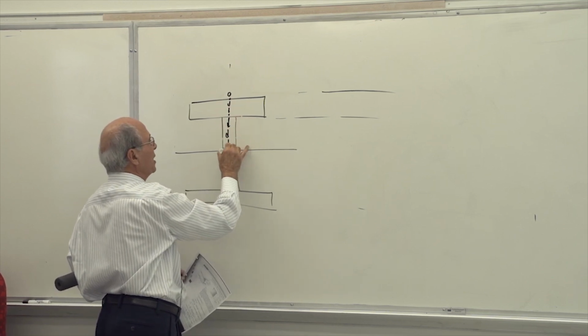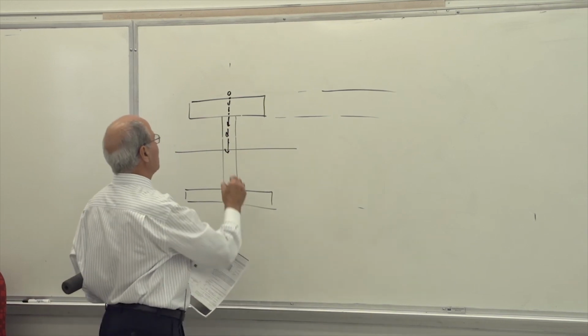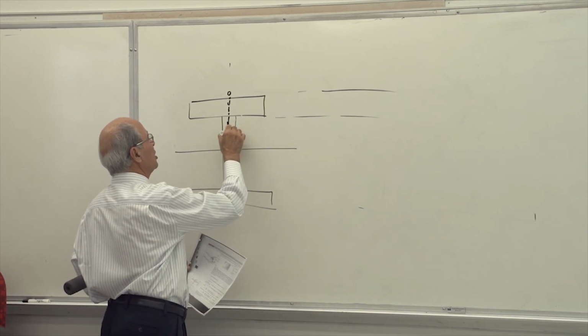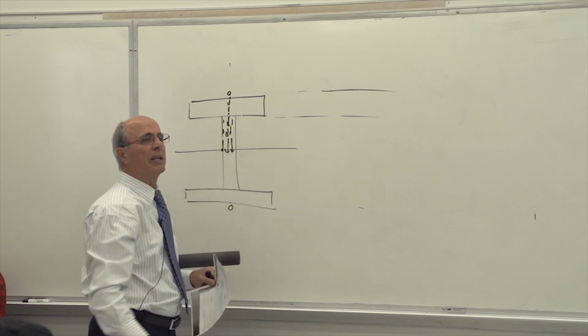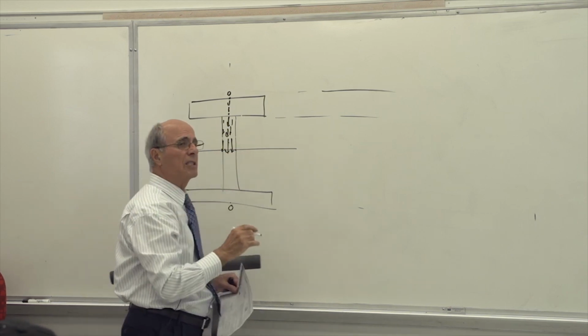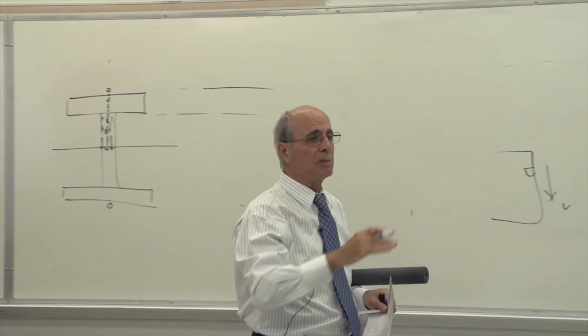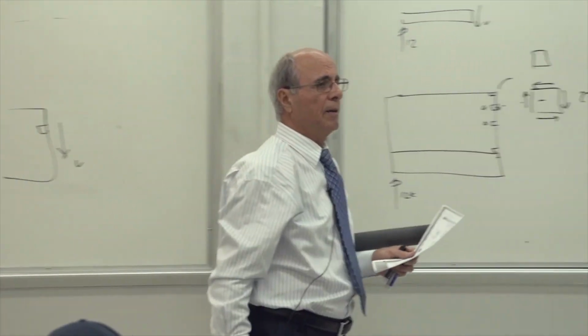Suddenly it becomes larger and larger, and the shear stresses, these are not shear forces, these are shear stresses, which is distributed like that. So the shear stress on the neutral axis for this beam becomes the largest, because Q becomes the largest value.